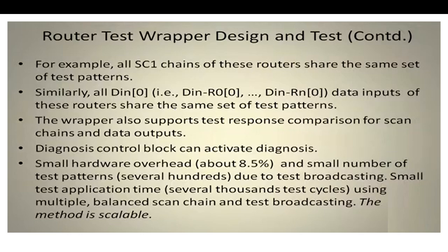Similarly, all D in 0, that is D in R of 0, D in R of N of 0, the data inputs of this router, share the same test patterns. The wrapper also supports test response comparison for scan chain and data outputs. Diagnosis control blocks can activate diagnosis.